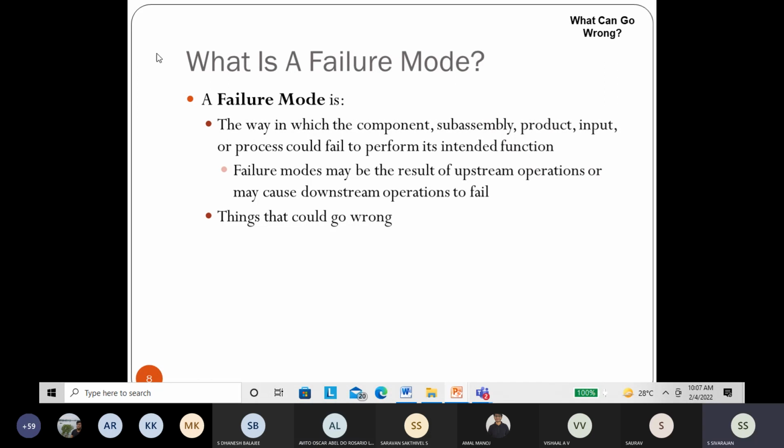CNC machine, no, we are programming it, because normally an oversized hole will come only in a manually drilled machine. On a CNC machine, unless the drill bit breaks, everything is controlled, and there is something called resolution of the machine. The machine movement is 10 micron. We can set the machine accurately to 10 micron, which means 0.01 mm. 1 mm is 1000 microns. So most CNC machines have a resolution of 10 microns, that means 0.01 mm. Up to that we can control.